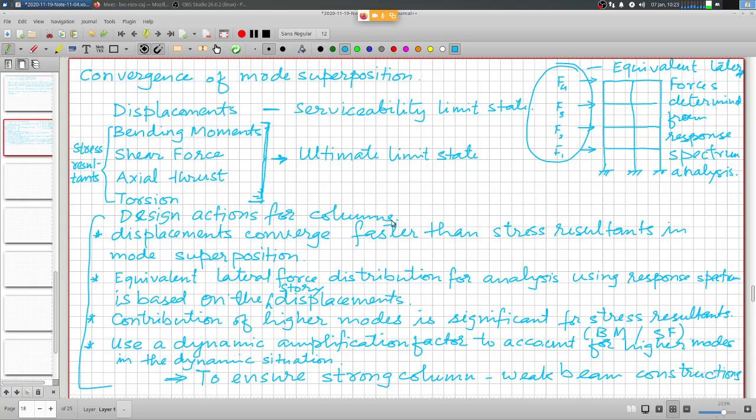But not just for tension. Even if the axial compression is very small, we can allow certain moment capacities to be reduced and inelastic deformations, hinging, to take place in certain columns, provided that the compression coming onto the column is very, very small.